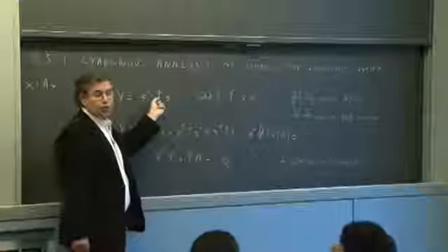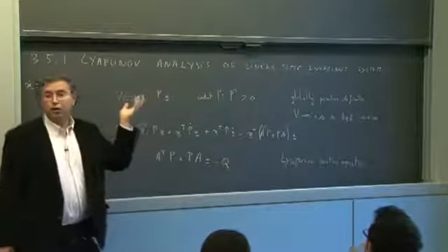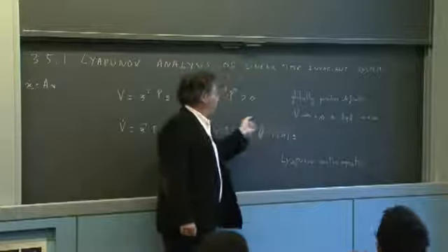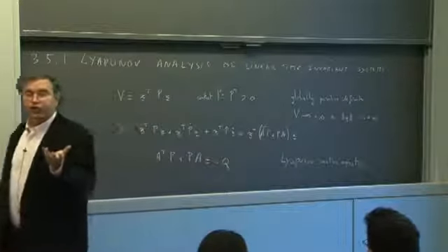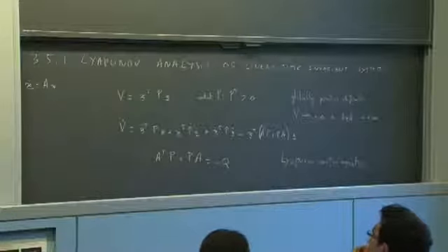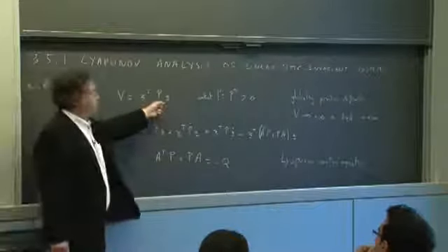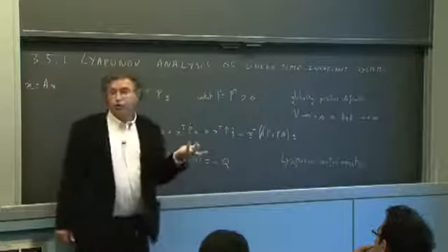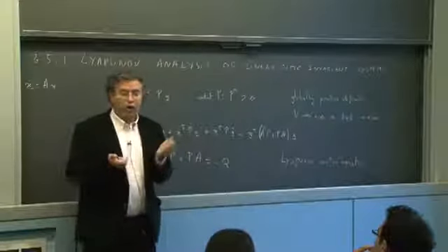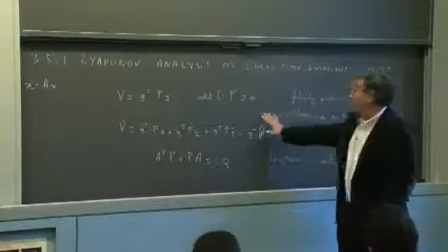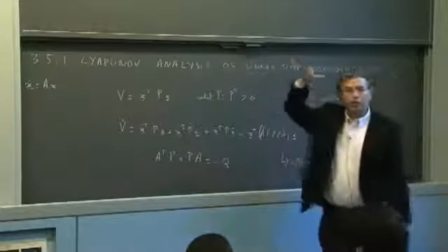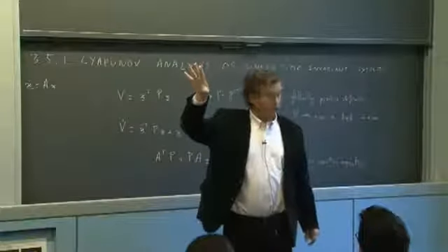One plausible question is, suppose I choose a P here which is positive definite, let's say identity. Then if the system is stable, is it true that the corresponding Q is positive definite? If this was true, you could pick an arbitrary P, for instance identity, and the corresponding Q given by this equation is positive definite if A is stable. Then of course this V dot would be globally negative definite, and you would be done using the global Lyapunov theorem for asymptotic stability.